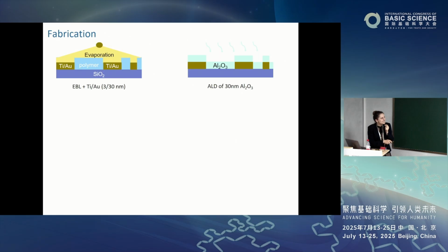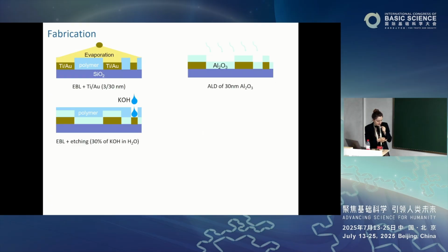Okay, next, we want to evaporate some insulator. We don't want to fry our flake, we want to gate it, which means we want to apply some voltage across an insulator so electrons feel that there is some potential behind the insulator, so they move, and we adjust the Fermi level respectively, but we don't want the flake in connection with gold. So we put some oxide as an insulator, and it's done by atomic layer deposition, so you deposit it atom after atom very precisely. So it's a very smooth structure.